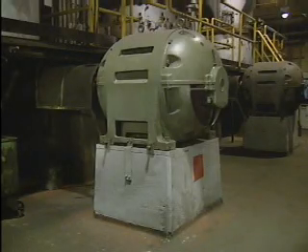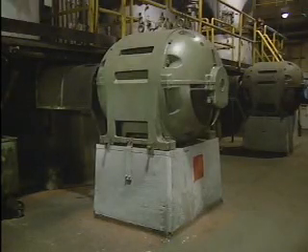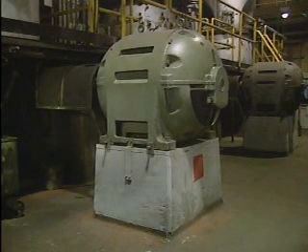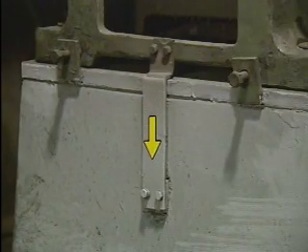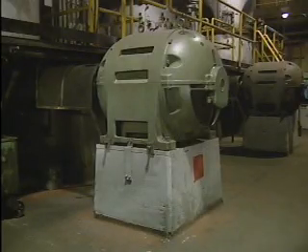Proper grounding is an important safety consideration for almost all electrical equipment. Proper grounding provides a low resistance path to ground for current that might otherwise go through someone's body. For example, this motor is properly grounded. The ground bus connects the motor's housing to a grounding grid that's buried in the earth. If the motor develops a fault, the normally de-energized housing could become energized. But through proper grounding, any current that's flowing in the housing because of a fault condition is directed to ground through the grounding strap and back to the motor's source of voltage instead of through a worker.